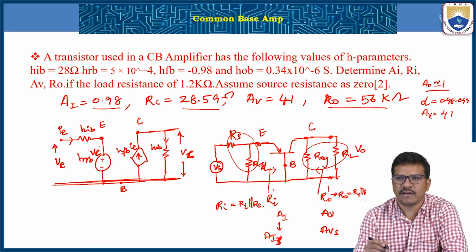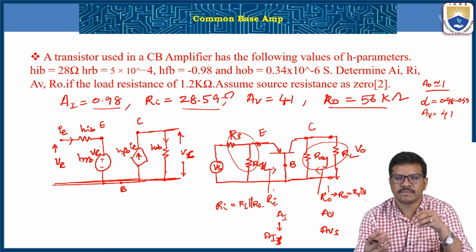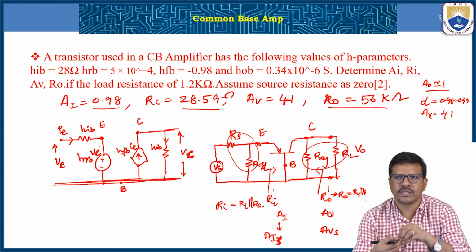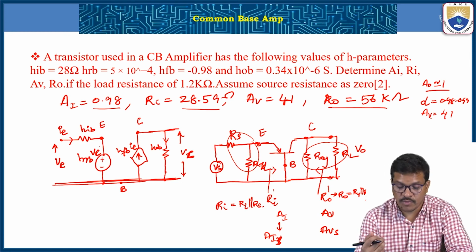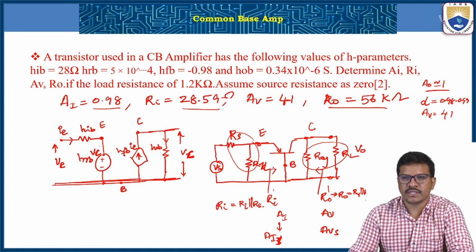We can use these kinds of parameters for the output circuit of the multi-stage amplifier. So when the input impedance is small, it is matched with the output loads. And AV voltage gain is large compared with the current gain. It will be used as a voltage amplifier. So most of the time by using these parameters, we can analyze where it will be placed in the multi-stage amplifier. So the common base configuration will be used at the output stage.